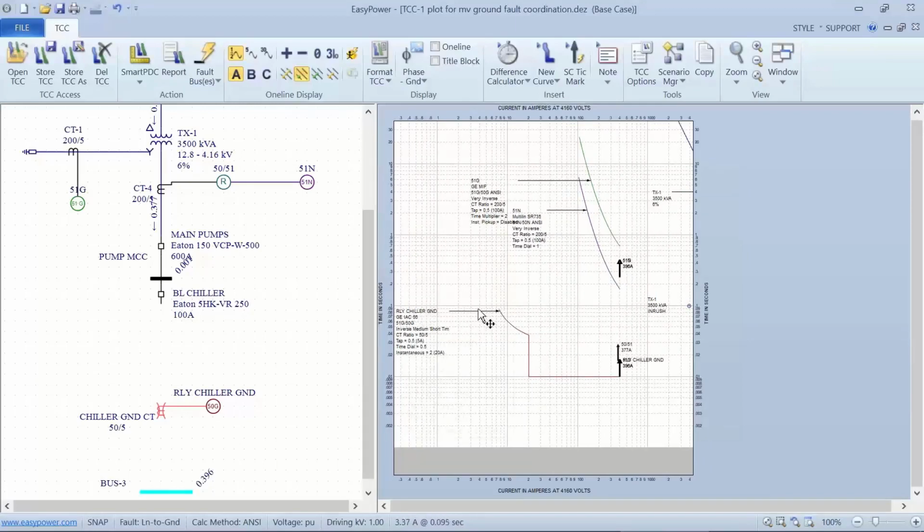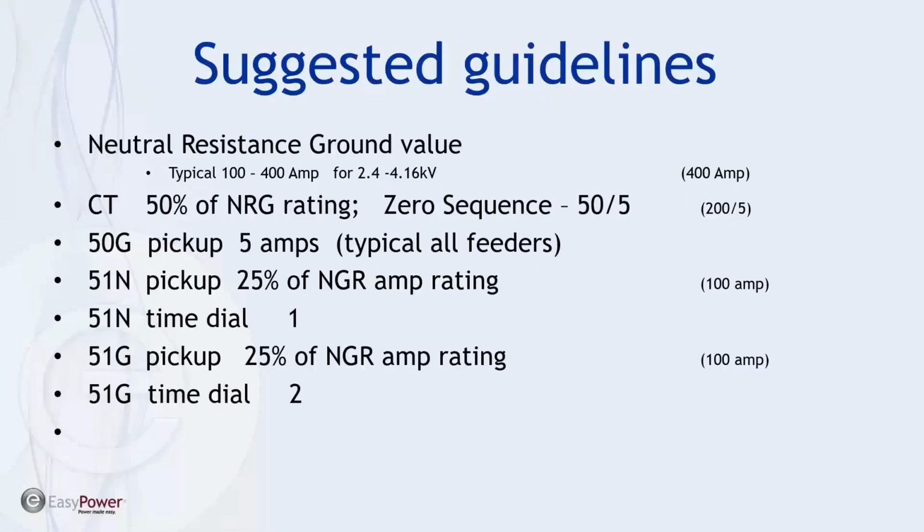The other significance is the tool has the ability to pick up on lower current and trip an individual section as a result. This makes it easier to troubleshoot if we have a low-level ground current before it elevates into a worst case situation. Okay, so let me see if we got questions. All right, so that's the medium voltage settings, and we're happy with that.